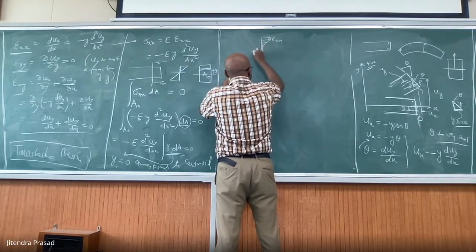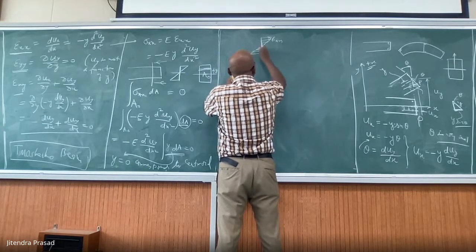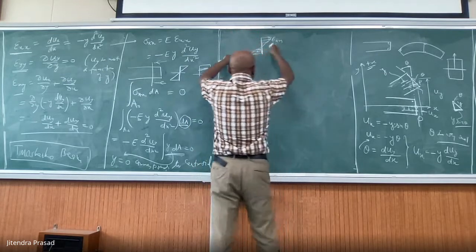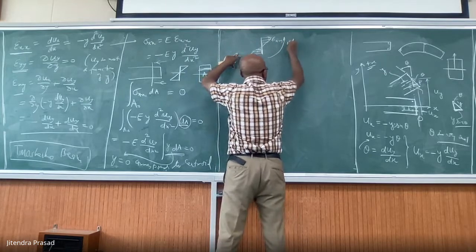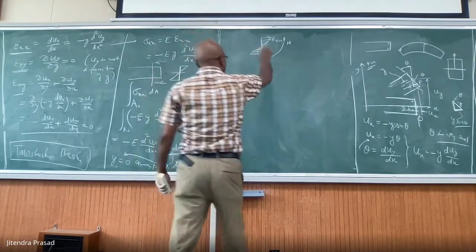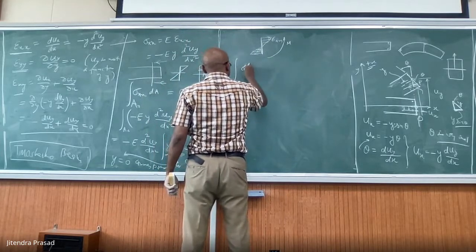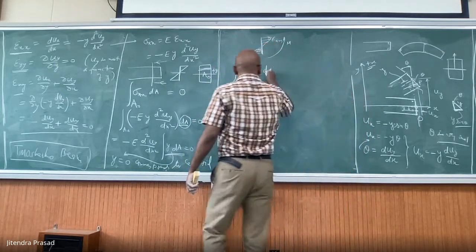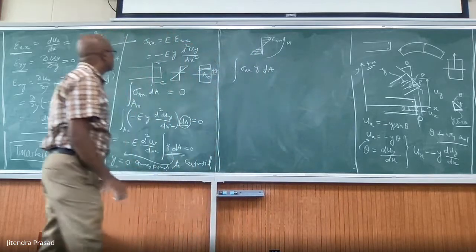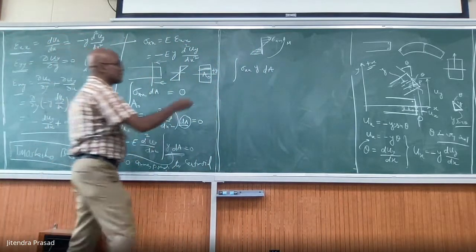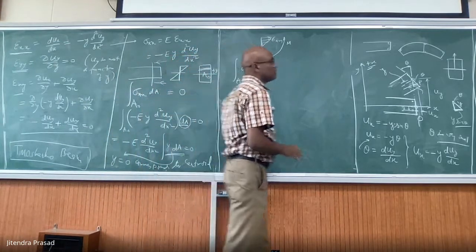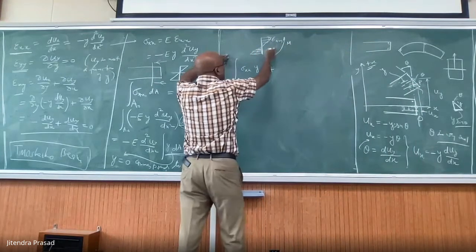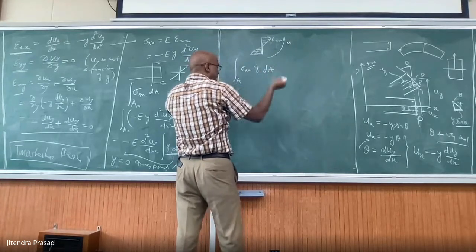This is a bending moment M. How do we calculate it? We calculate sigma xx multiplied by y dA over the whole area. Sigma x is positive here, and if you apply a bending moment like this, what happens?